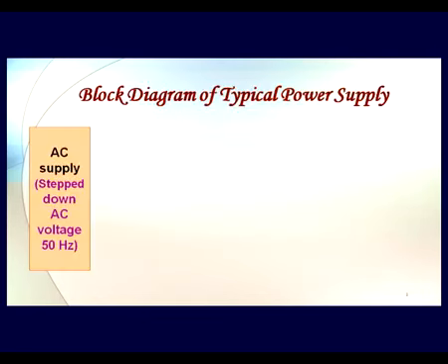So here diagrammatically I am showing step by step that we have an AC supply of 50 Hertz frequency, that we first step down. Let us consider that we have a requirement where we need a voltage lesser than 230 volts. For example, take our battery charger or a cell phone charger, which typically requires 5 volt DC. Then we first have to step down that 230 volts AC to a level comparable to 5 volts, something like say 10 volts.